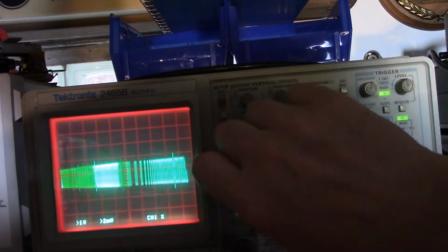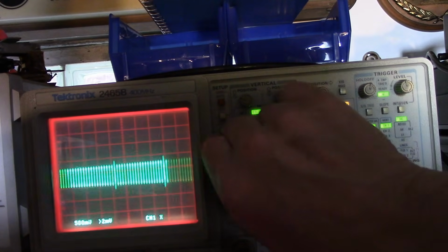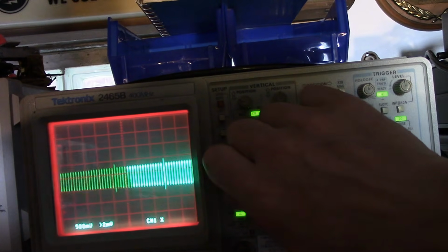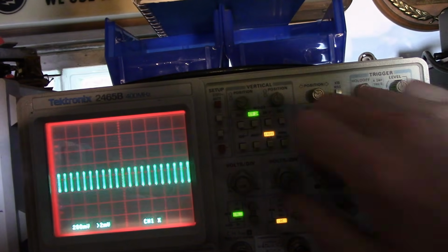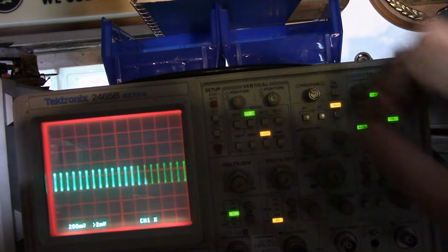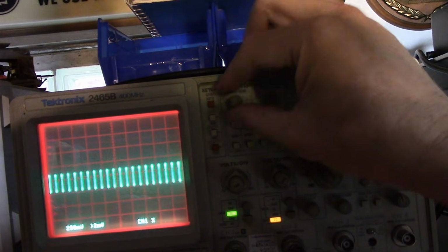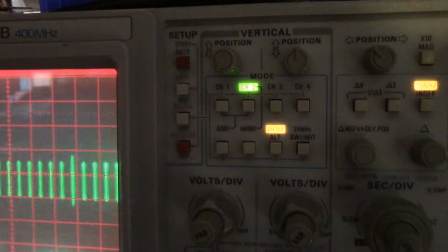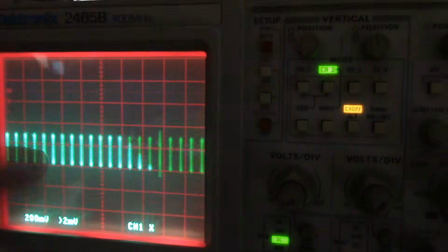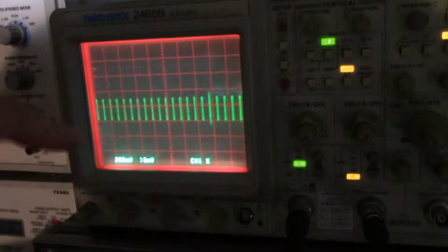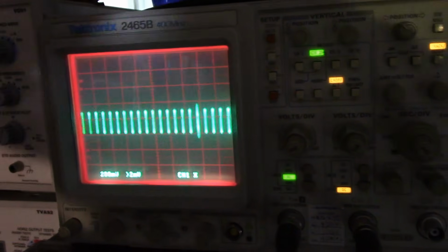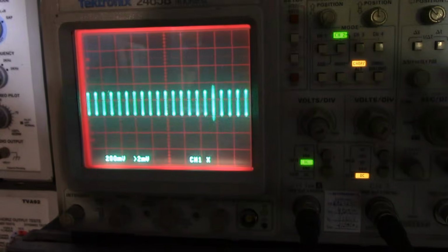Trying to zoom in here so you guys can see one closer up. So that's it right there. I can also just hold down the button for a marker and you get that, but it's nice to get this. And those distinct striations, as I've mentioned before, this is a digital sweep generator. It goes in discrete steps, it's not continuous, so you have gaps in the frequency coverage. But it should be good enough for our purposes.